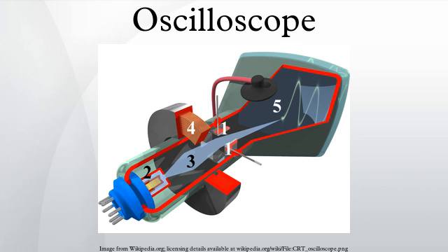Types and models. The following section is a brief summary of various types and models available. For a detailed discussion, refer to the other article. Cathode-ray oscilloscope. The earliest and simplest type of oscilloscope consisted of a cathode-ray tube, a vertical amplifier, a timebase, a horizontal amplifier and a power supply. These are now called analog scopes to distinguish them from the digital scopes that became common in the 1990s and 2000s. Analog scopes do not necessarily include a calibrated reference grid for size measurement of waves, and they may not display waves in the traditional sense of a line segment sweeping from left to right.